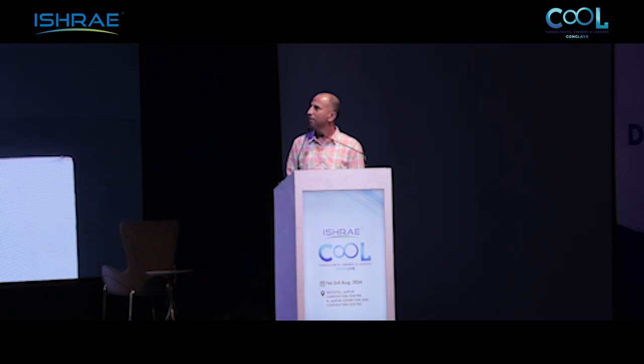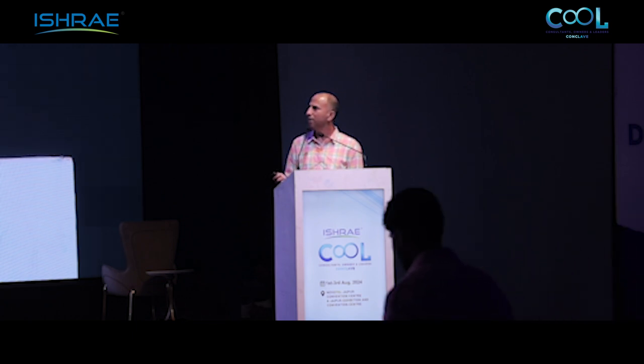Now, this is a not-in-kind technologies classification as per the RTOC assessment of the Montreal Protocol. They can be classified as widely commercially available if they are produced by more than one company, commercially available if it is produced at least by one company, emerging if they have undergone R&D but are still not commercialized, a research and development phase if they are actively doing R&D but not yet fully established. There could be some other technologies having limited use in special applications like deep sea or lake cooling, which is best done in a district cooling kind of setup.